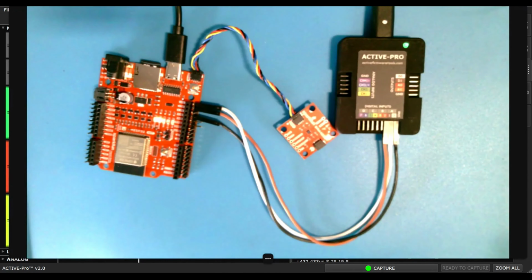We're going to write some code to tell it to send out some special commands so we can see some information from inside this microprocessor on the debugger. We're going to pick these 2 pins. You need one to be a clock, one to be data, and we are going to wire those up right now. Okay, so here we have the extra wires attached. We've got 2 channels going to our clock and our data coming from the microprocessor.